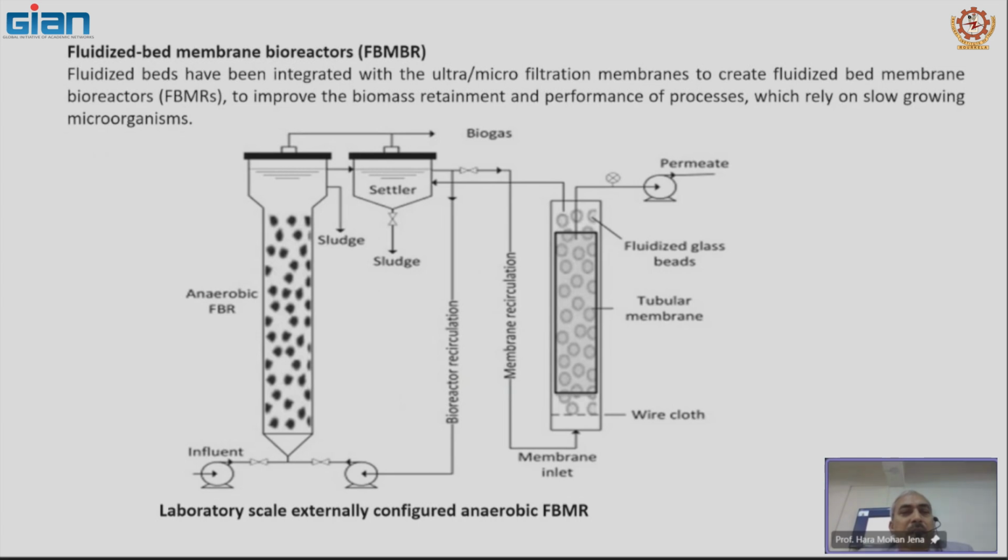Then fluidized bed membrane bioreactors are also in use. Fluidized beds are integrated with ultra or microfiltration membranes to create fluidized bed membrane bioreactors, to improve the biomass retention and performance of the process, which relies on slow growing microorganisms. You can see this is the anaerobic fluidized bed reactor and this is the membrane unit.